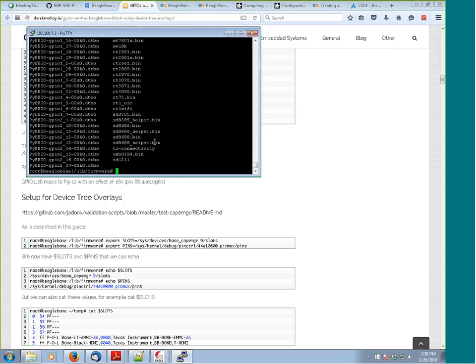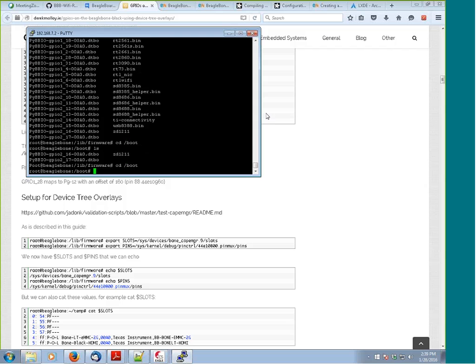So again, we're here. Now, because I chose to not do the EEPROM, I had to figure out a way to get the device tree overlay to load up at boot. Otherwise, every time I turned on the radio, I would have to go in SSH and basically apply the overlay. So, a couple of things that you should be aware of if you're doing the same thing. Let's go to the boot directory. There's a lot of important files here. The most important one is uEnv.txt.